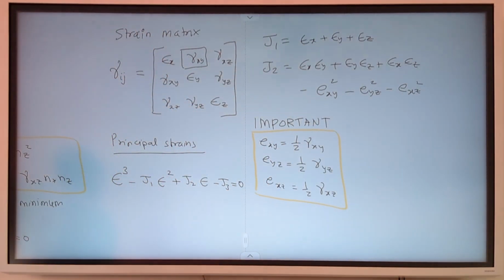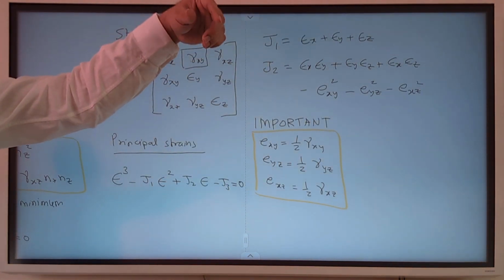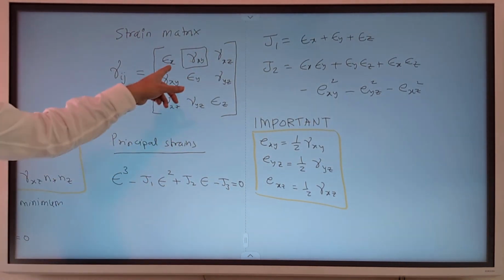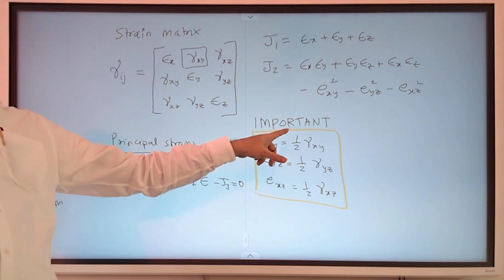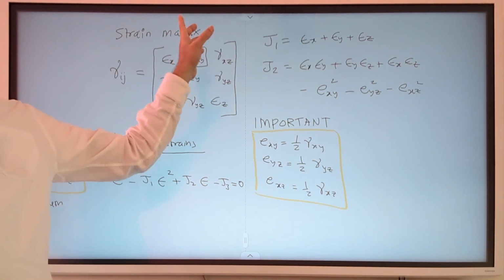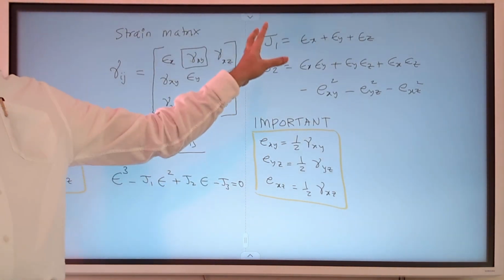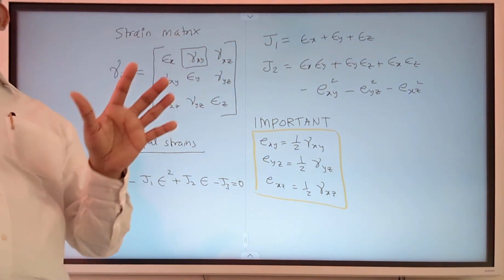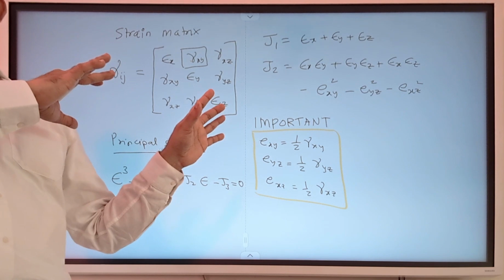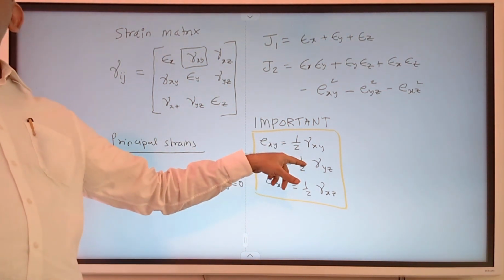So this is the common mistake that one would make in exam, or I find at least 10% of you make, even after telling this is important. Somehow you directly pick from this matrix and then solve the problem. You have to remember that while calculating principal strains, only the shear strain terms are to be halved, the linear strain terms remain the same. We are not going into the derivation of that, so luckily you are saved from the complexity of how this has come. But those who are interested, in the book you can go through why this particular thing is there.